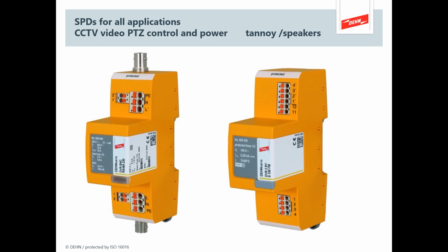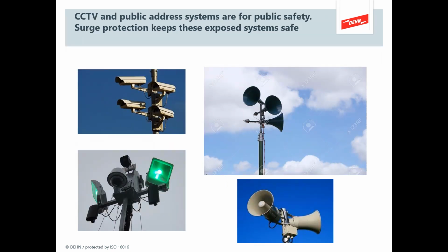And another version for external applications would be public address, tannoy speakers, that sort of thing. So if there's a situation at a military site or a shopping mall, you would want these safety circuits, these public address systems, to work. So we have some specific SPDs just for these applications. And here are typical applications. So they're all mounted outside, they're all on poles, they're all likely to get zapped by lightning, and this is why we have these new developments in SPDs.